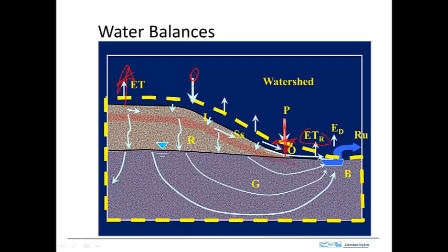This thing, ETR, is riparian evapotranspiration, so that's going out. This ED is direct evaporation, evaporation directly off the water surface. That's going out. Runoff is going out, surface water runoff. And down here, this is groundwater flow, and so we've got some groundwater flow going out. Things like recharge don't really count because that's just a flux within the region, it's not crossing the boundary, and it's not representing storage. So that's not going to enter at all in this particular analysis.